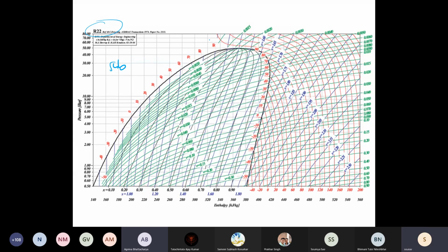Whereas you see these isothermal lines coming out from the saturated vapor region, these red colored lines, and they are going over here in the superheated region. As you move further away from the dome, these isothermal lines look almost like isenthalpic lines. Only near this region and the supercritical region you see them curving.